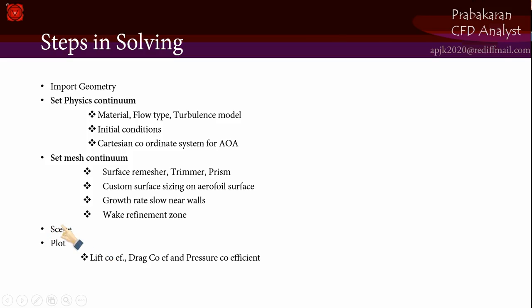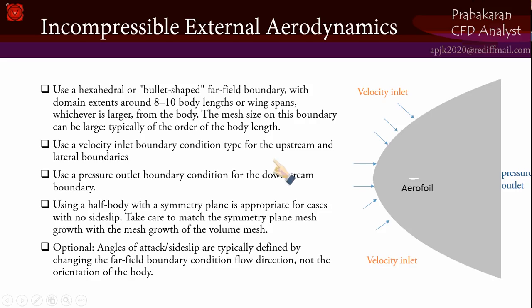Thereafter, in order to visualize our solution, I will be creating some scenes which are essential, and I will create some plots which are our objectives, which are the lift coefficient, drag coefficient and pressure coefficient. Finally, I will compare the lift coefficient, drag coefficient and pressure coefficient calculated from Star-CCM+ with a software called JavaFoil. Okay. So that is our final stage. So this is the methodology I am going to use.